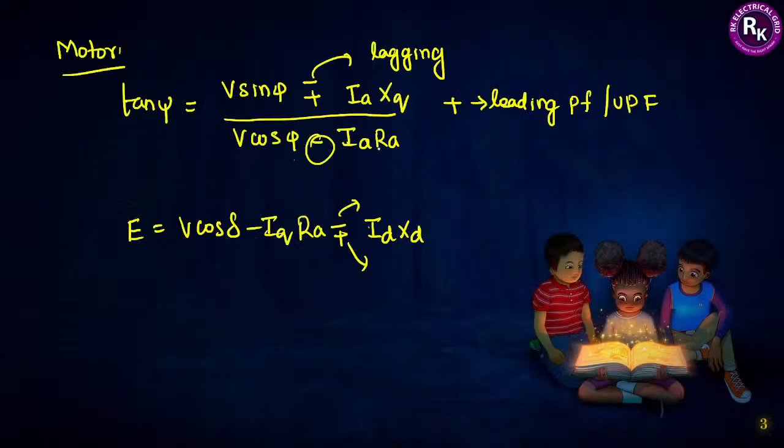We have discussed the basic internal power factor angle. I hope you all know this. This is output, that is external power factor angle, the relation between voltage and output current, that is external current, armature current, and this is quadrature reactance. This is armature resistance, and this is the total armature current taken by the machine motor. V is phase voltage, terminal voltage.